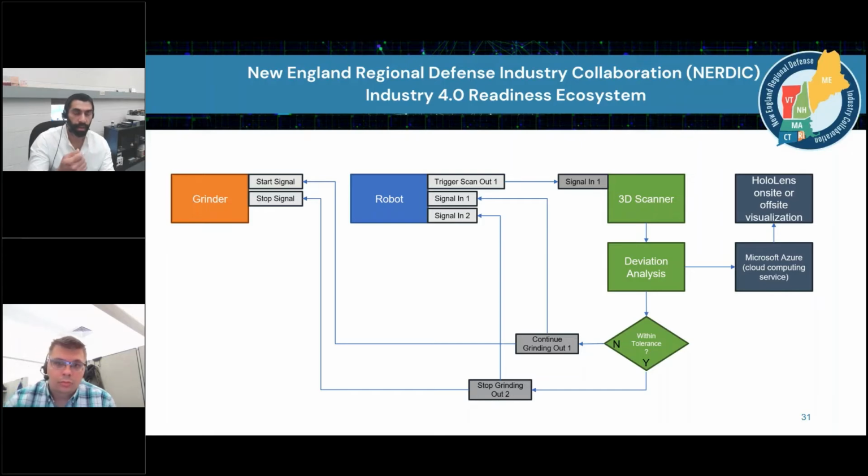Normally, if you think of taking a used part out of an assembly, for example, a turbine blade out of an engine, and you do an inspection on it, at that point you determine this is out of spec, it's no longer usable. What you would do if you were to go down the route of component repair would be to map out where exactly the wear is on the part using some inspection technology.